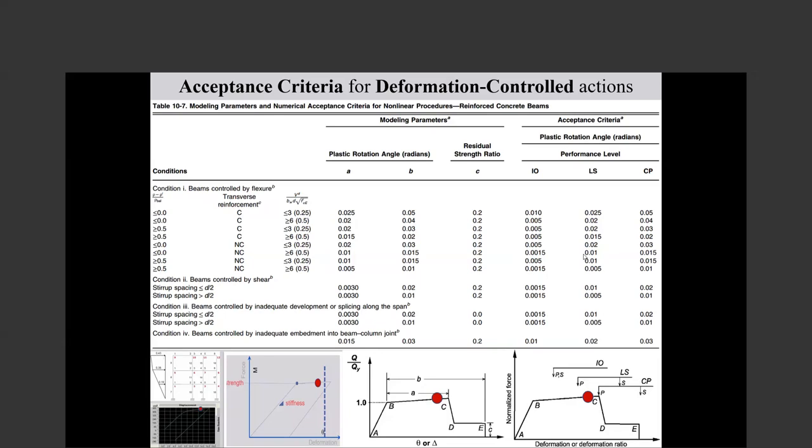But the other type of new building code that applies nonlinear static or nonlinear dynamic, they say that you model, do pushover, do nonlinear dynamic. Then when you want to check the acceptance criteria, refer to the codes for the existing buildings. So this way, they solve it.